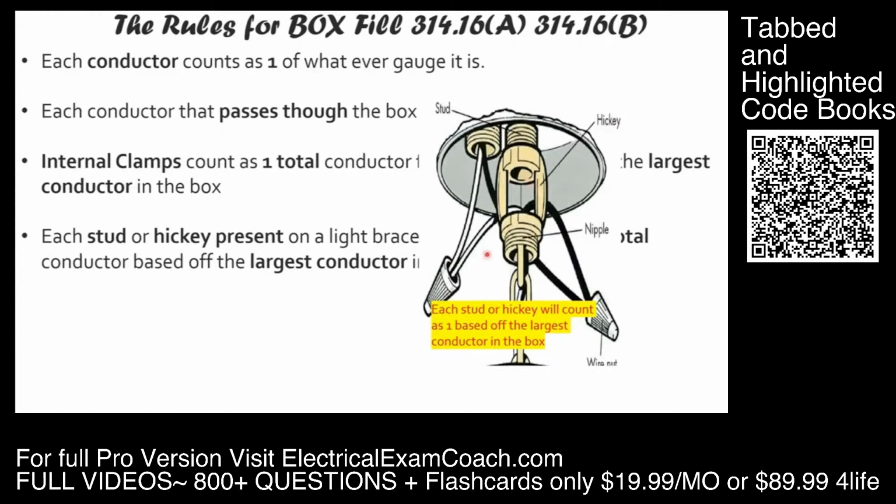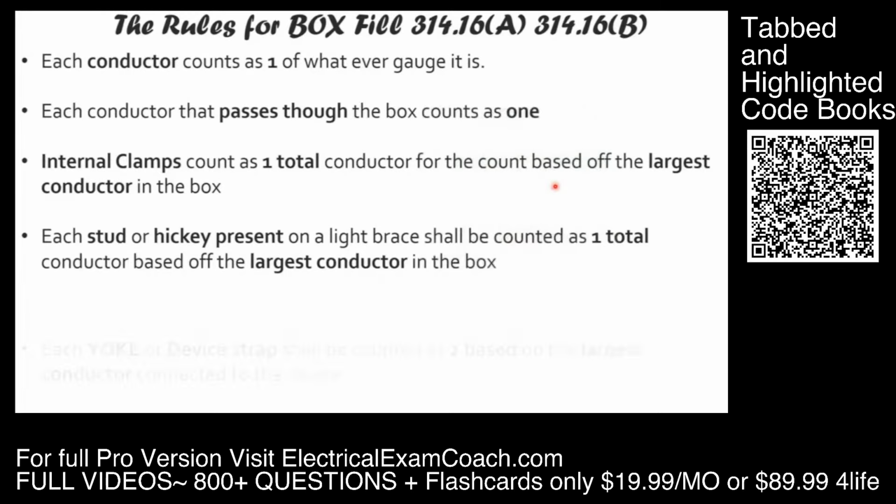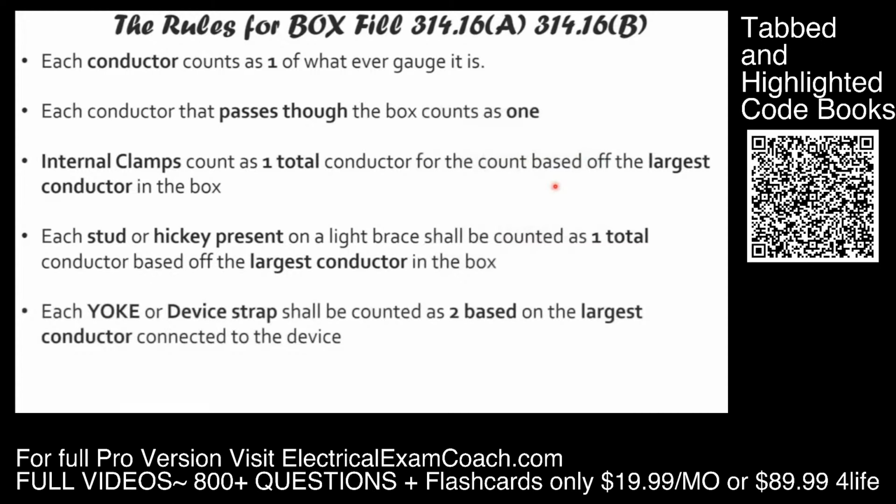In this scenario here, in this picture, the stud would count as 1 of whatever gauge was in the box that was the largest, and the hickey would count as 1 of whatever gauge was in the box that is the largest. And we're going to do lots of practice, so don't worry about it. Now we need to account for device straps and yokes. What the code states is that for each device strap or yoke, it's going to be counted as 2 based off the largest conductor that's connected to the device.